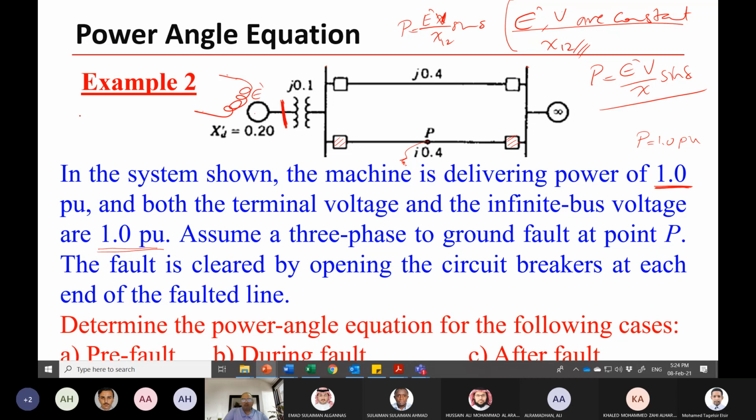You probably know the internal voltage of a synchronous machine is 4.44 times the frequency, times the flux, times the number of turns per phase. Of course, we also have the winding factor, distribution factor, and the chording factor, but that is not the problem here.